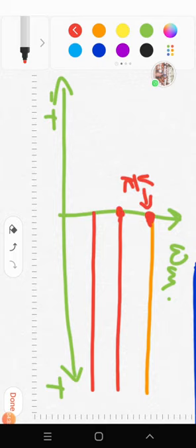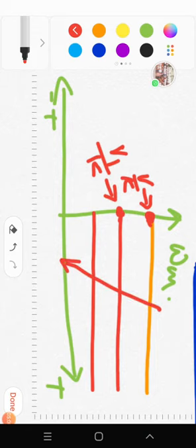Then we change the V by K, and what change we can make? We can just reduce the V, we cannot increase the V because it will be like giving over voltage to the motor. So we can give smaller voltages to the motor, and due to that the characteristic can be shifted only downwards in this direction. So again, if we change V, it will be like this. So in this way there will be change in the V.